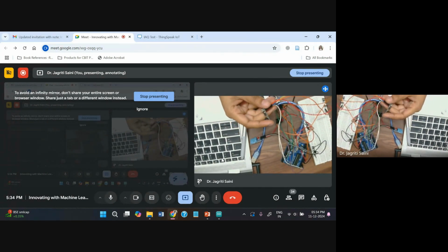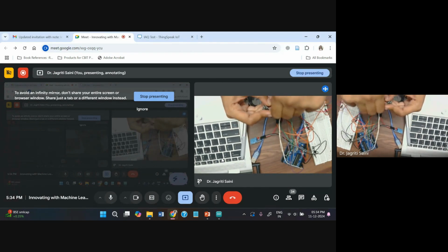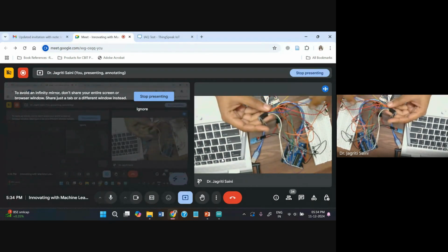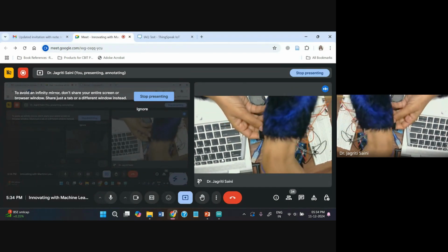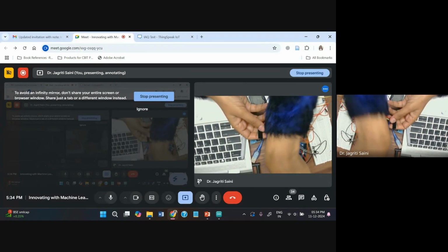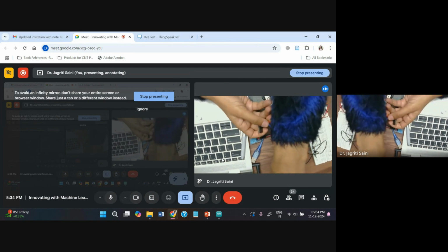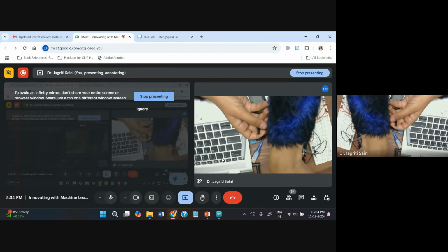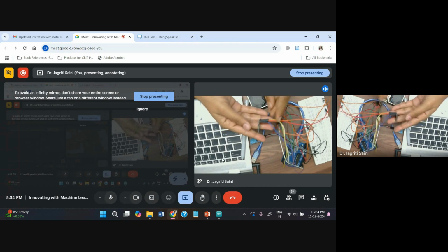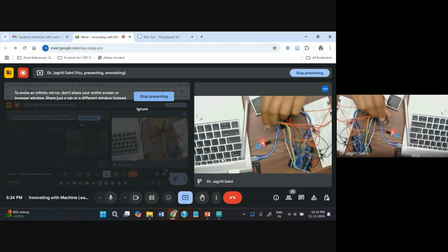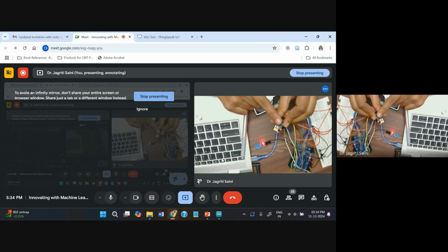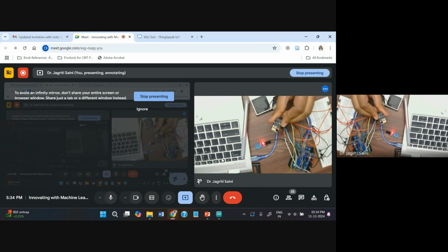The remaining wires, one is receiver and other is transmitter. And I told you that this ESP will be using the hardware serial. So the receiver I'll be using on the transmitter right here, and the transmitter I'll be using on the receiver right here. And as soon as I connect my wires again, you will observe a red light on this sensor, and as soon as it connects to the Wi-Fi.